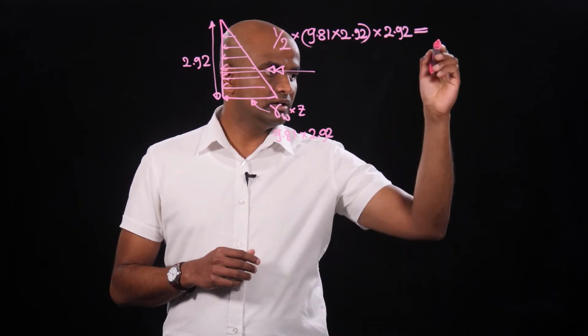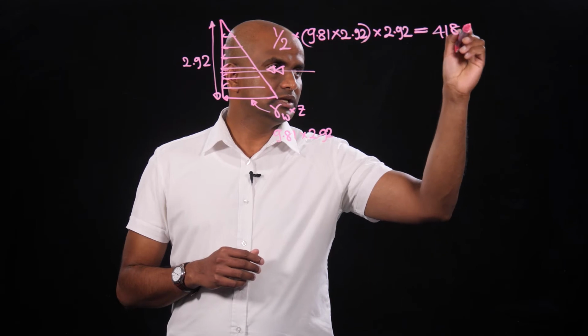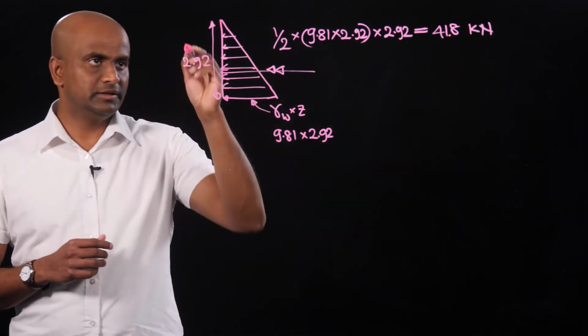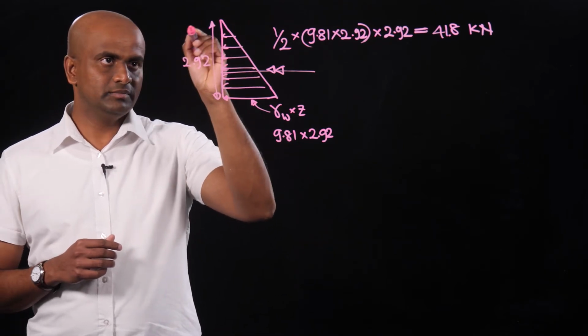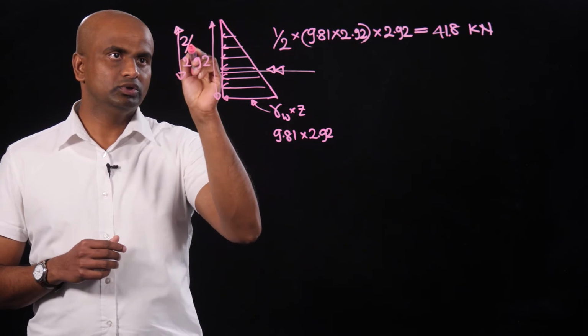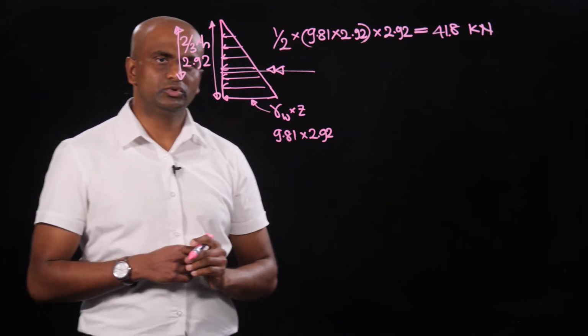So that will be 41.8 kilonewton, and that will be acting at the center of gravity, which will be here at 2/3 of the height, which is 2.92.